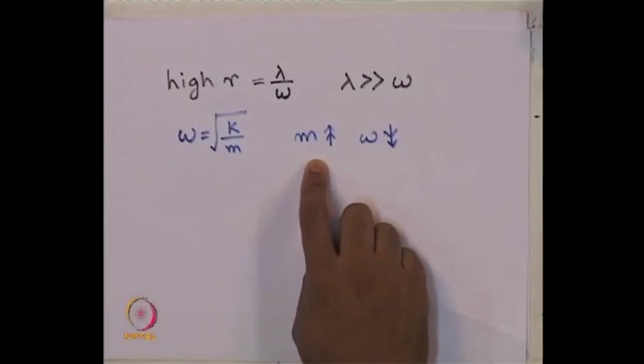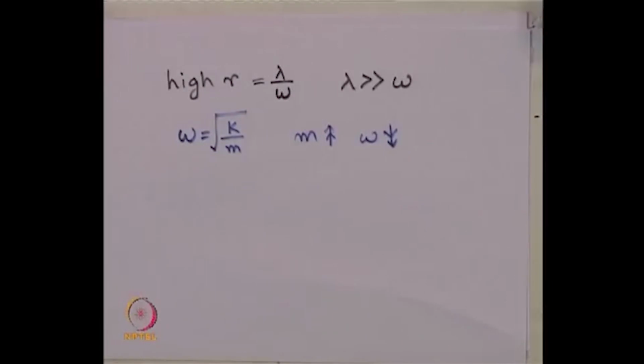Now, let me make you understand in a better way what happens physically. Externally applied frequency is pretty high and the system is very rigid. So, why is the dynamic displacement less than the static displacement? What is the physical significance? It means you are applying a very high frequency to a rigid system, and its mass is so heavy that it is not getting enough time to respond. So, its dynamic displacement is less.